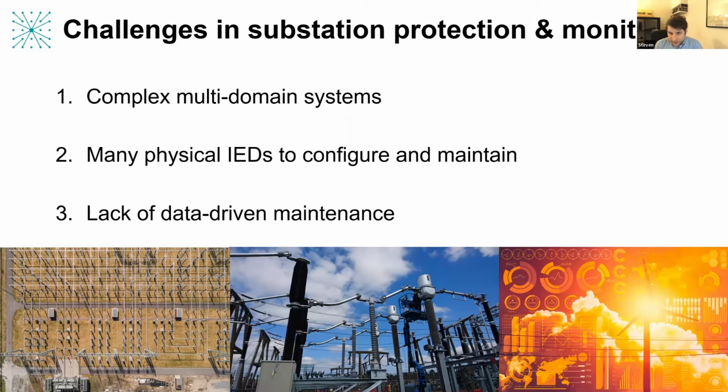And the third point I just wanted to highlight today was that typically SCADA systems don't provide a very high resolution of monitoring, and even relatively advanced monitoring schemes using PMUs can actually miss some important events, such as fast-acting transients in the system, like arcing of a circuit breaker or maybe chattering of relay contacts.